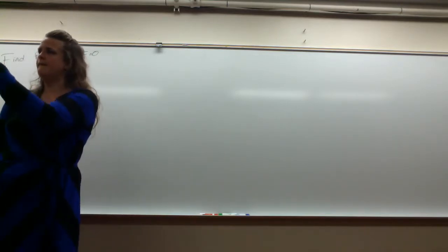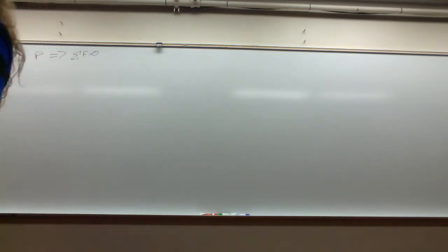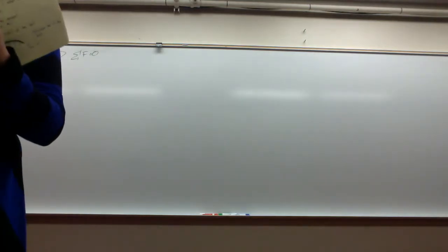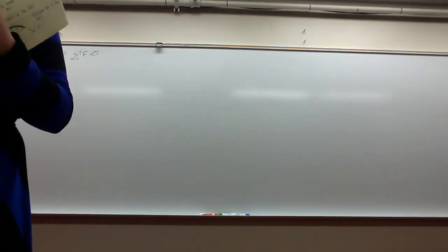Smaller, why? Kind of, yeah. But what else is going on that we're not taking into account? Friction, right? That friction is holding the load. It's assisting P. So friction is aiding the force P.